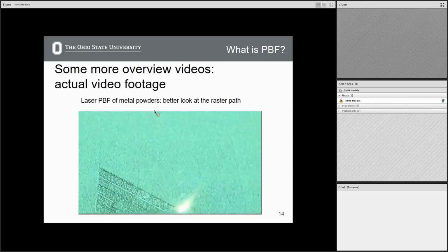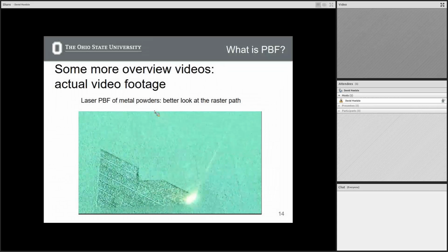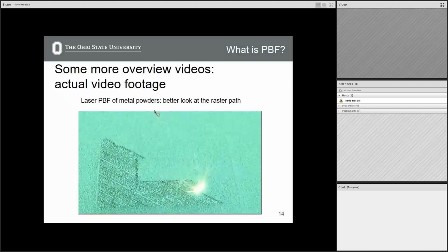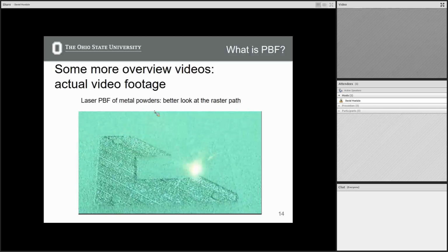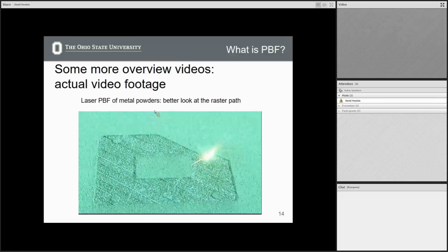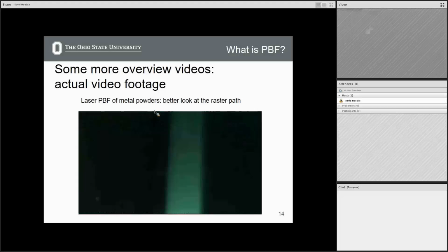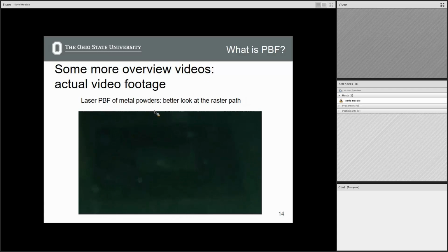You can see how the laser is going really fast back and forth. Even though it looks like a line source, it's actually rastering back and forth really quickly. But this nicely shows these bands that are going side by side. You also see sparks flying off, right? Those either vaporize or remain as little small parts of metal that could cause problems. You also may have noticed that at the very end, it very quickly circumscribed the entire part.